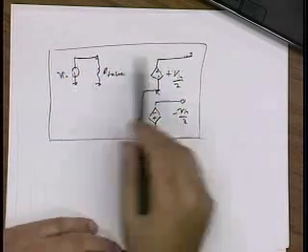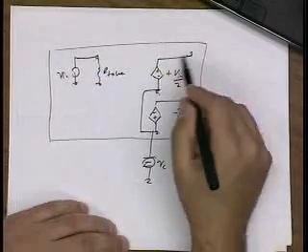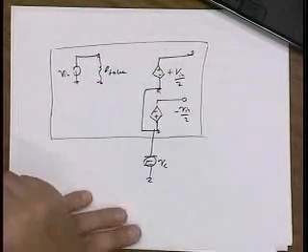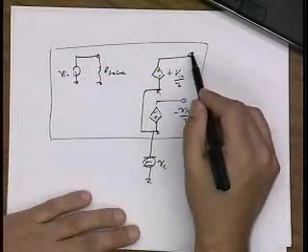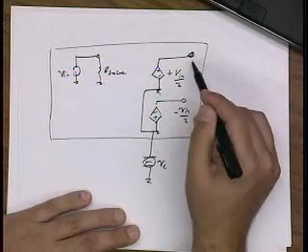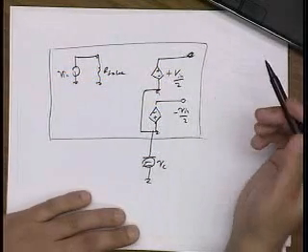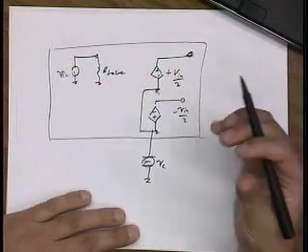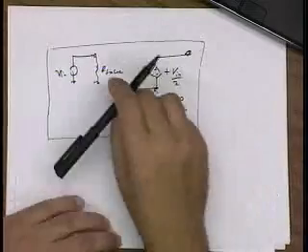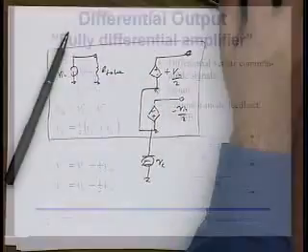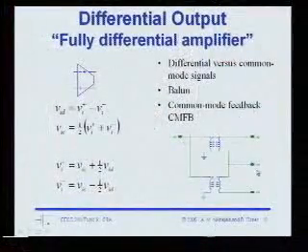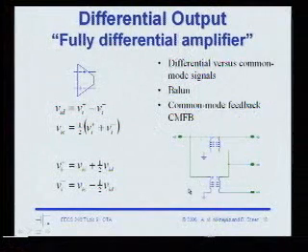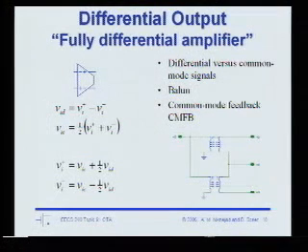Well, one of the issues with this circuit is that the source impedance now is 0. What I'd really like to do is drive my circuit with the right source impedance. And likewise, if I put a load on the circuit, I want to make sure that I'm truly loading the circuit. So this is why baluns are actually very convenient. So let's switch here. Now, I'd never actually use a balun, but this is just for SPICE. So in SPICE, it's very convenient to use baluns to generate differential mode signals.